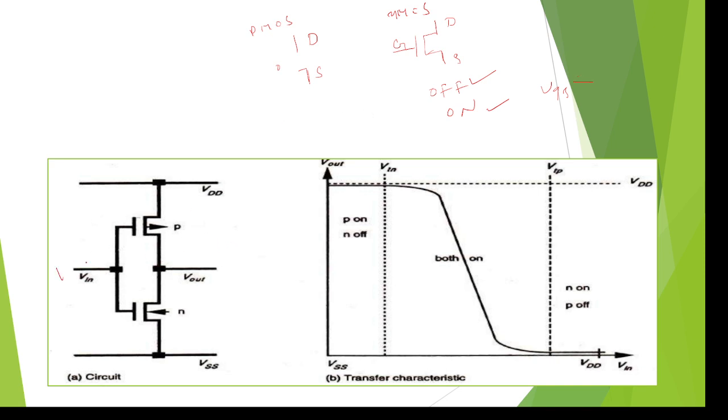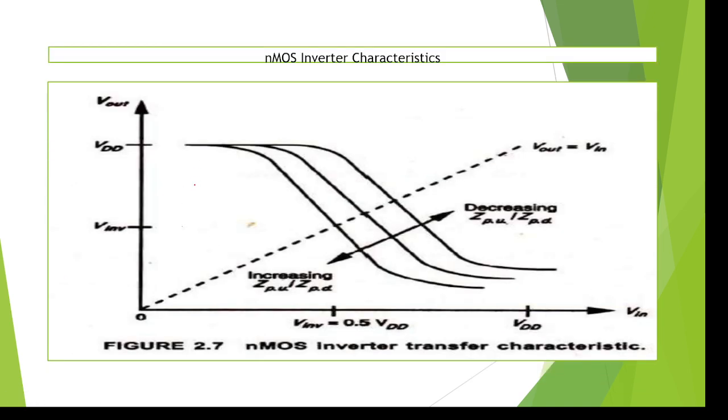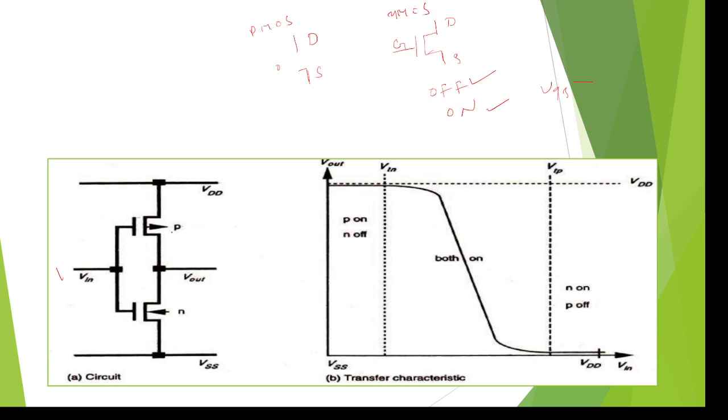How will it get there, we will check. We can see this when we are giving binary 1. This is a PMOS transistor, and it is like a PNP. Just an assumption, there is no sufficient VGS here actually, so this transistor will go to off condition. And this is an NMOS transistor, it is like an NPN.